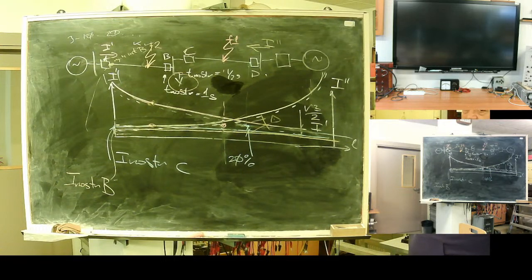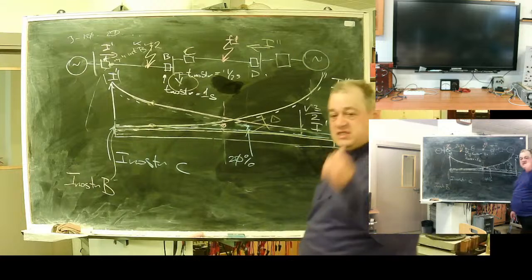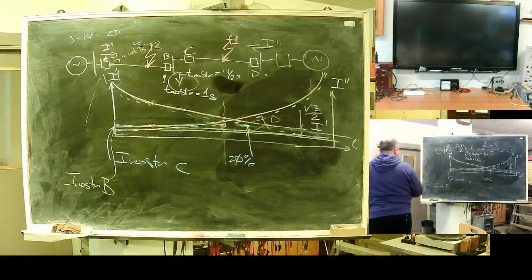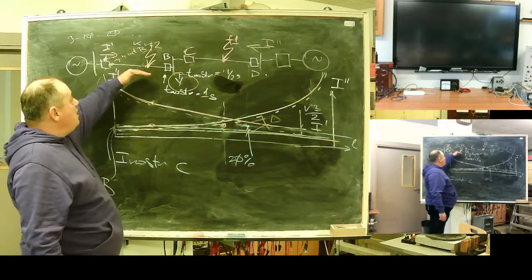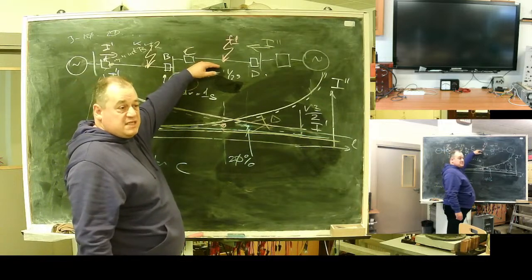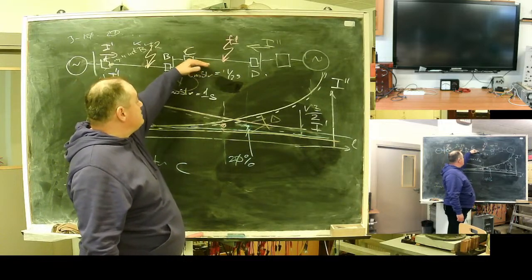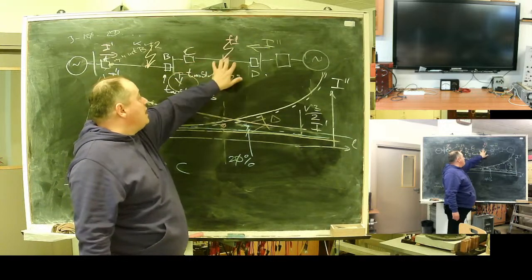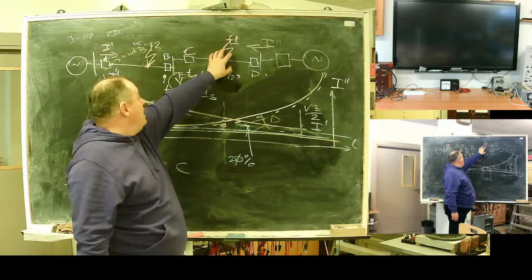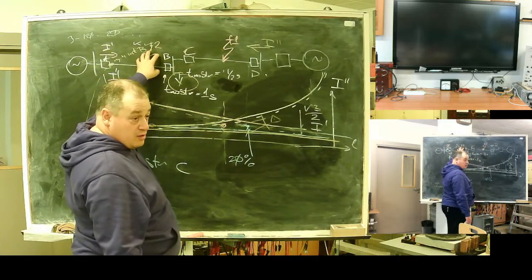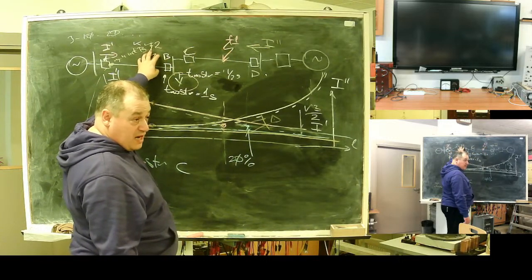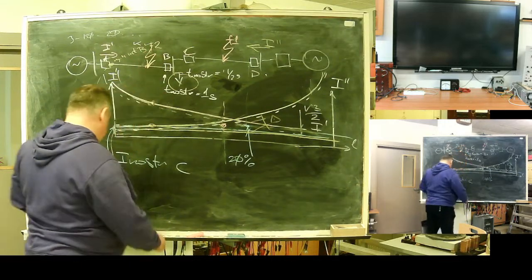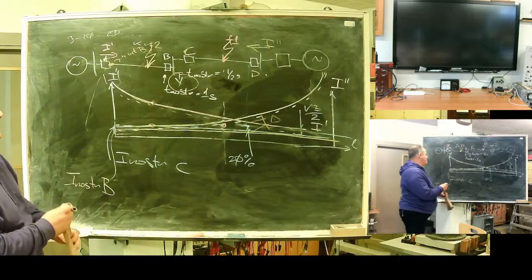Again, you will see false trips on the fault behind. See the problem? For example, for these relays, C relay cannot discriminate between direct fault in line, or fault behind the back, or reverse directed fault. We need to do something.